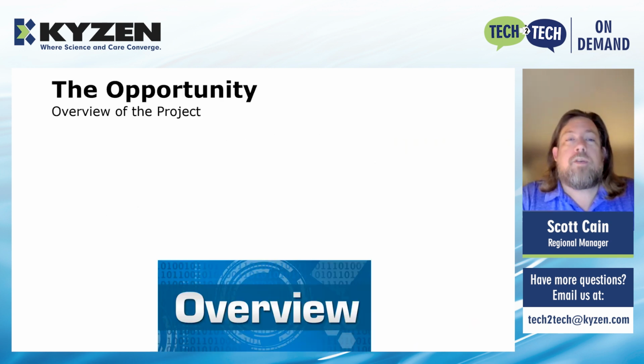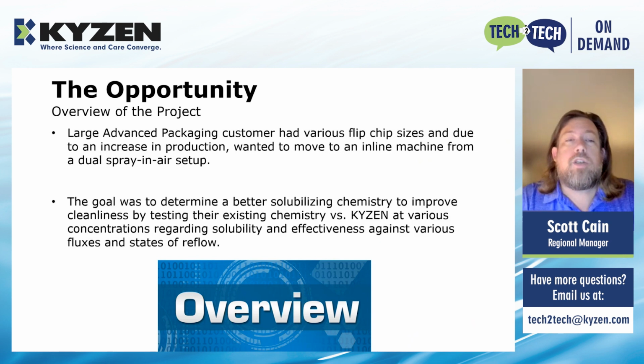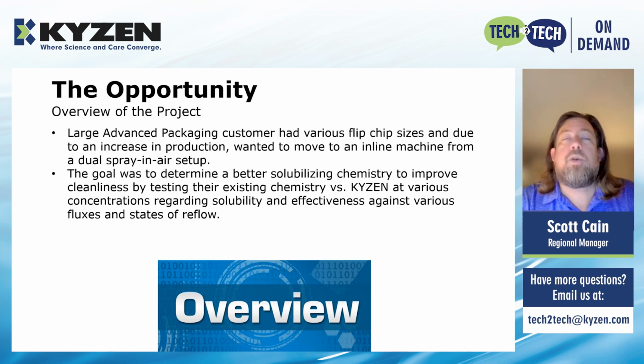So, what was the opportunity or the overview of the project? What we had was a large advanced packaging customer. They had various sizes of flip chips, and due to an increase in production, they wanted to move to a new style of machine. They weren't sure if the chemistry was going to be able to work in the new style of machines when they went to an inline machine. And they wanted to check the solubility of the existing chemistry versus Kaizen at various concentrations and against various states of fluxes and reflow. And they had sent us 5 fluxes, but they were anonymous. They didn't tell us what the fluxes were, so they were just labeled A through E.